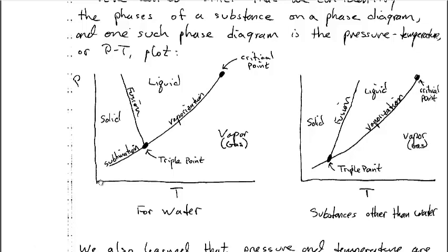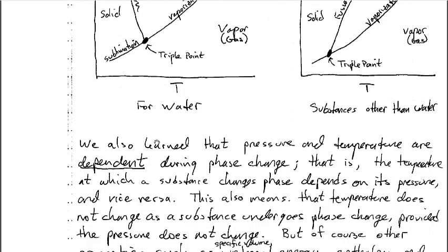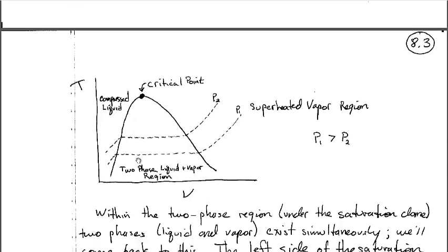So if you can kind of imagine pulling that pressure temperature plane, pulling that in the third axis dimension, what happens with this vaporization curve is it becomes a dome. And that's what we show here on this temperature volume diagram. So this dome that you see is the vaporization line that has been extruded in the third dimension from a pressure temperature plot.